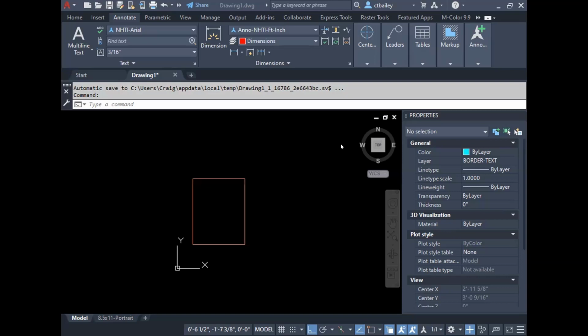Now, select your object in the polyline again, this line. But look at the difference, look how the stretch frame slices through the horizontal on the top and the horizontal on the right bar. And it wholly contains that right hand vertical, right? Yeah. You check this, that's the stretch to the right only.